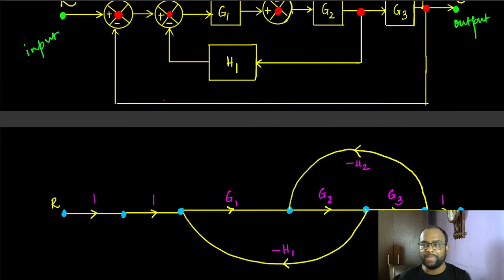So buffer circuits will be everywhere whenever you are constructing a controller, so that the current limitation is properly held. For example, if you are using a microcontroller to construct an electronic circuit or a control system, the pins in the microcontroller would have a current limit. For example, 40 milliampere is the current limit on a pin.